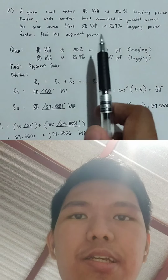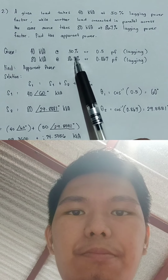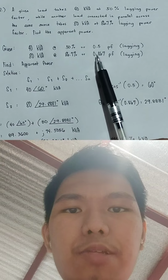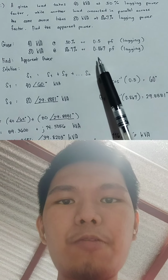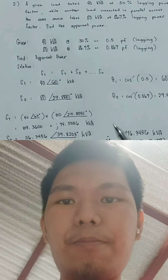As we can see, the lagging power factor given here is in percent, and we will convert it to decimal. 50% will become 0.5 and 86.7% will become 0.867 power factor. Since both are positive, it is lagging.